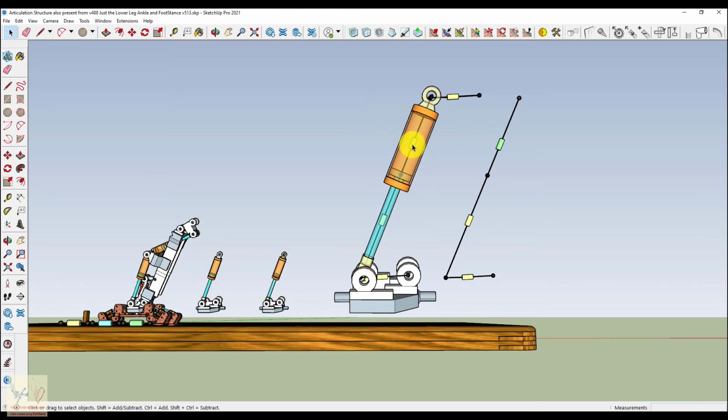But this controller here of this cylinder is a slider controller when it is connected to this controller, because this does not rotate, it slides, so it's a translation motion, not a rotation motion. So when you have a translation motion, I'm calling it a slider, as opposed to a swing arm, which is a rotation motion.